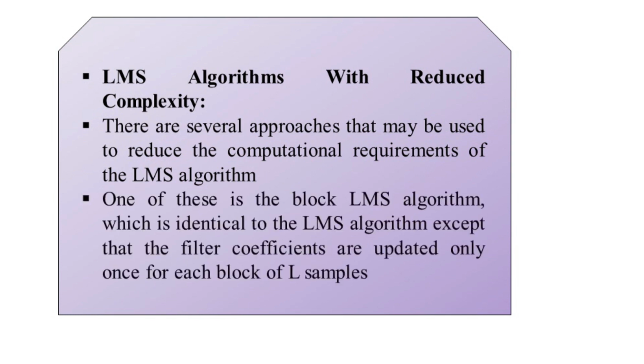In other words, the filter coefficients are held constant over each block of L samples, and the filter output y of n and the error signal e of n for each value of n within the block are calculated using the filter coefficients for that particular block.